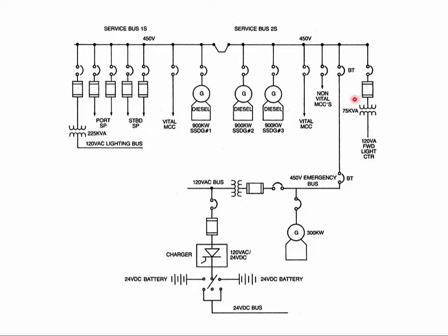Some people also test the emergency diesel generator startup by opening this bus tie down in the engine room, and then your generator will start up. Though typically I like to do it using the provided switch, which is on the diesel generator control panel.